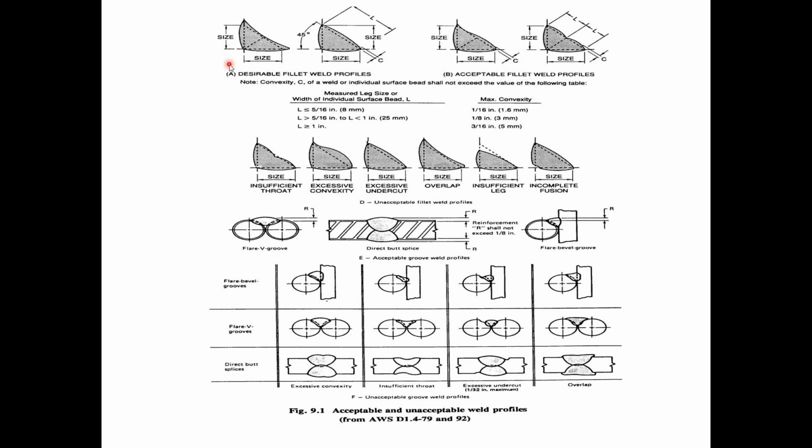So you can see there that that gray shading exceeds the nominal dashed line on all three sides. So we've got more weld there than is needed. There's no area where we're less than what that dashed line is. So that's desirable.